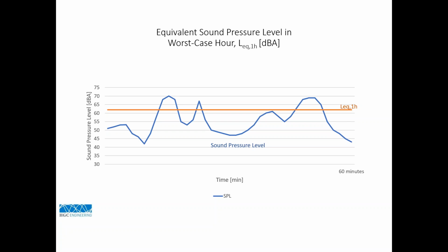As the trucks go in, and as other activities are happening, and the tanker trucks come in and go out, and the front end loader passes, the sound level is never going to be steady. But essentially, the level that your consultant is going to assess is one number that represents the logarithmic average of the intermittent sound levels that are occurring at your site.